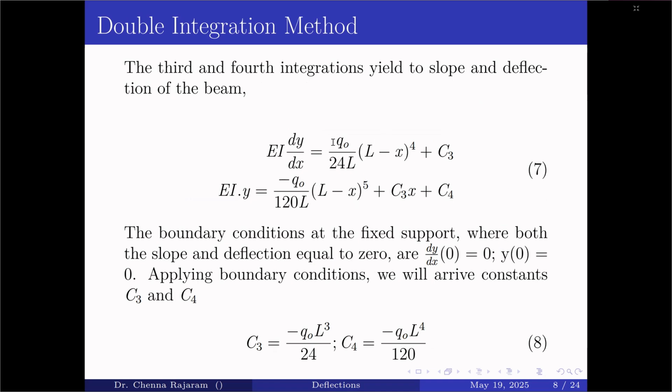Similar to the shear force and bending moments as I explained in the earlier case, again you take one more integration, that is EI y to obtain the deflection, which is equal to minus q0 divided by 120L into (L minus x) to the power of 5 plus C3x plus C4.